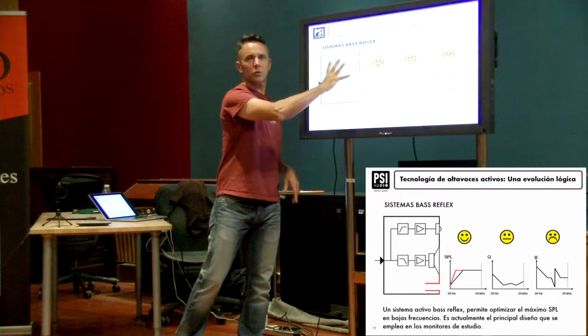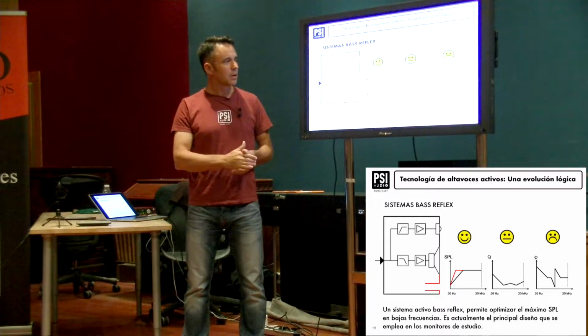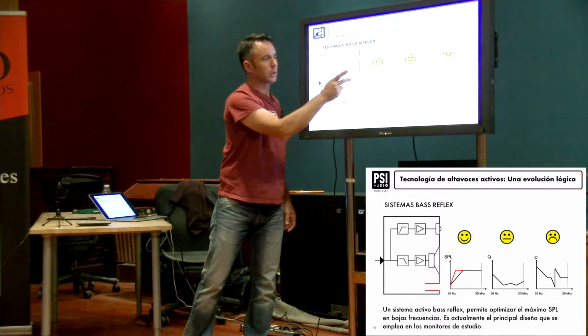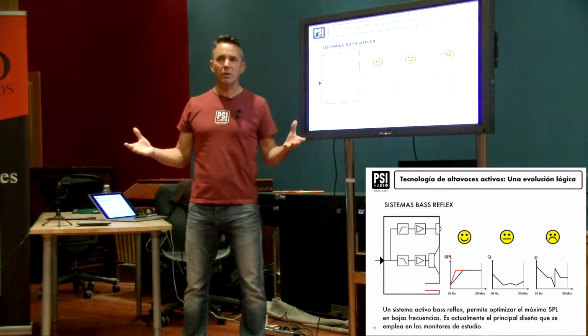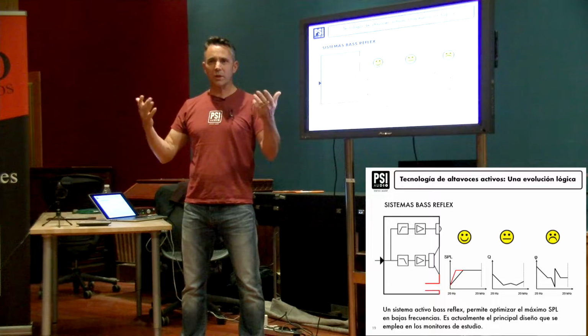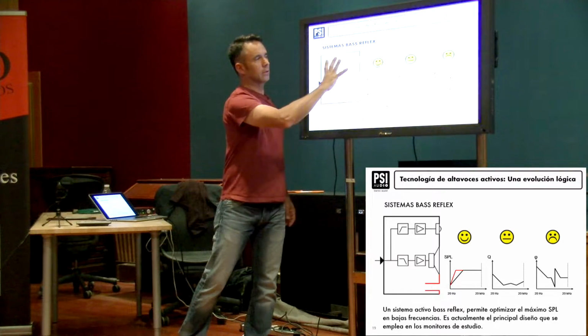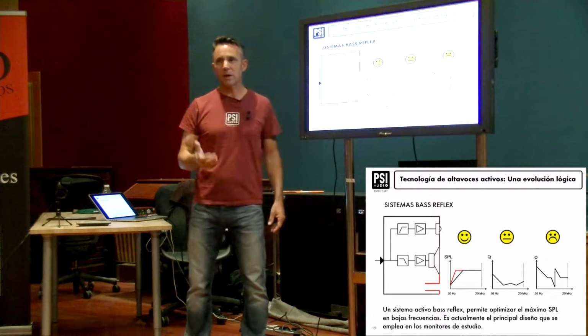So what we do is we build a resonator with the cabinet and make sure the resonator resonates at exactly the right frequency that will complement what comes out of here. Okay, so it's a resonator. A resonator is, again, mass on springs. Here we have the mass that is the air inside here, and the spring is the air inside here, and it's activated by the back of the membrane.